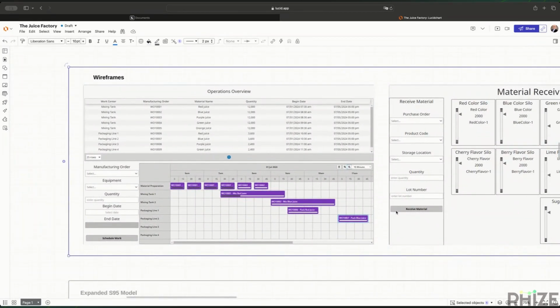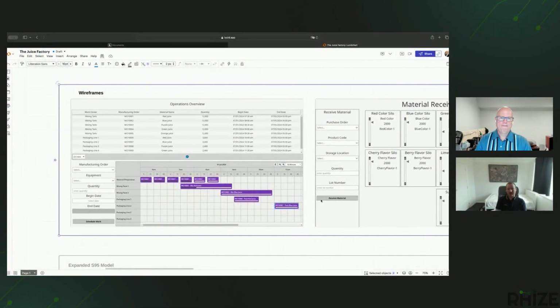Yeah, I think probably two comments from that. You can definitely see the advantage of it being a headless MES / data hub there, where you can implement the front end however you want, and it's very changeable on top of the existing data structure. And I think you also really see the advantage of ISA-95 there with the different containers containing, so you've got a process segment that contains the operations definitions and things like that.